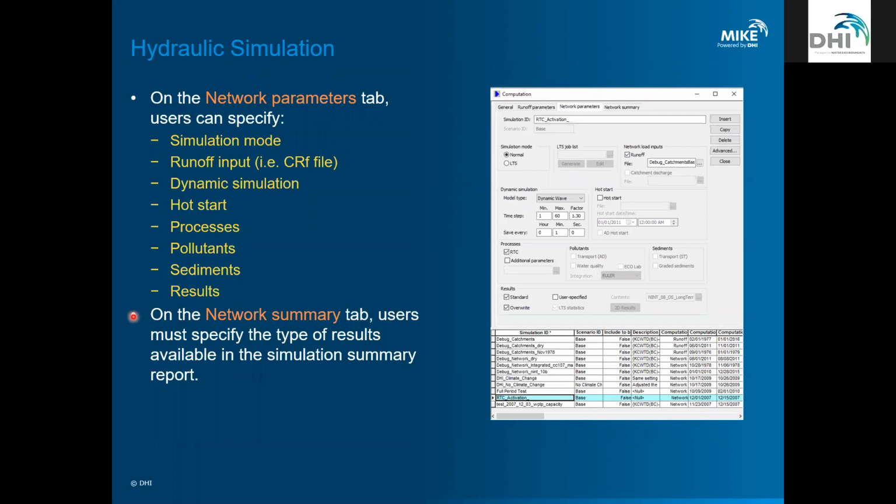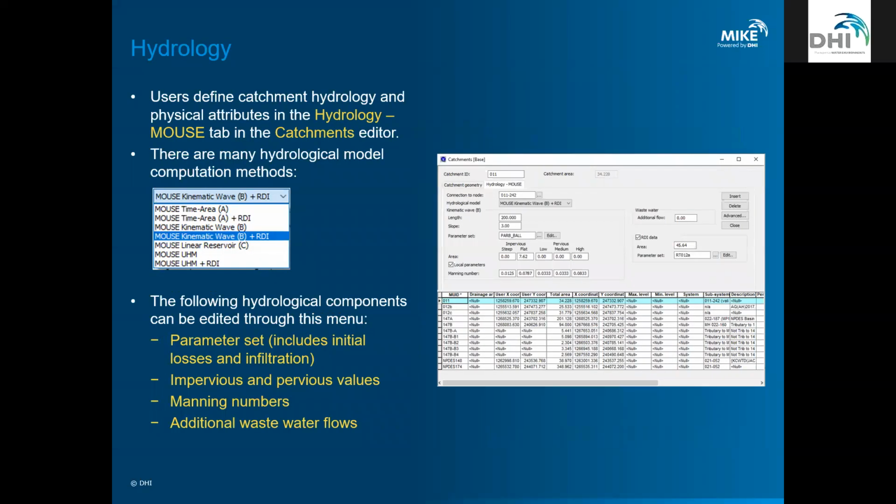There's a question about the hydrology tab. So there's a bunch of options there. For the catchment basin specifically, it's going to be in the menu under the mouse menu, where you're going to see catchments and catchment parameters. That is where you will come up with this editor where it says catchment space. And then there are 2 tabs there, one is the geometry and one is the hydrology.